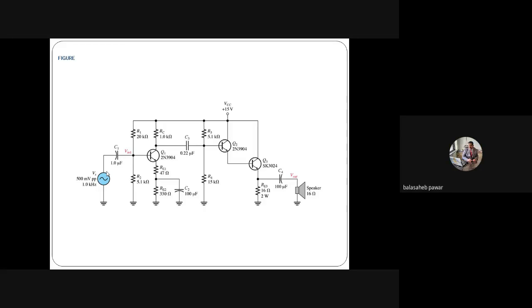As we are thinking about DC analysis, meaning only DC components, all capacitors, such as C1 and C3 which look like they are in series, will act as open circuits for DC components. They provide infinite reactance, 1 upon 2 pi Fc. As F is zero, since we are considering only DC components, the reactance provided by all capacitors is infinite, and that's why in general for DC analysis all capacitors act as open circuits, right?